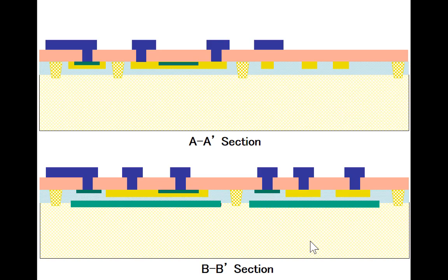Okay, so what do we have? Here's our flagship device. This is a vertical NPN transistor. It's called a vertical device because it stands vertically in this device. We can now see the purpose of the buried collector. It's a hassle to get access to the contacts of that vertical transistor. We don't have any way to make electrical contact underneath it. So what we did was we put this buried collector, which is a low resistance region.